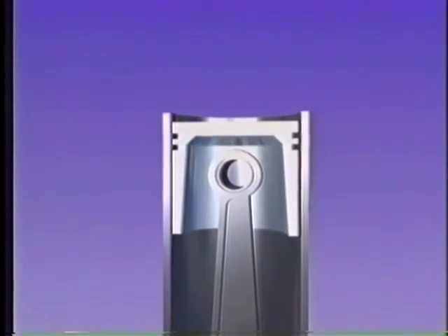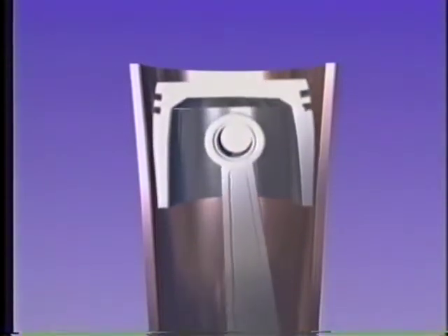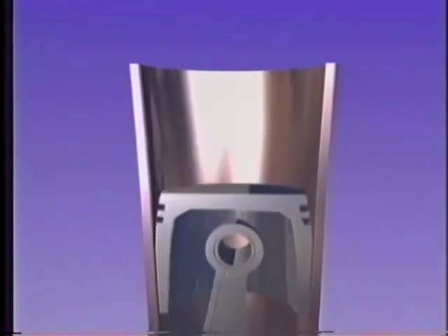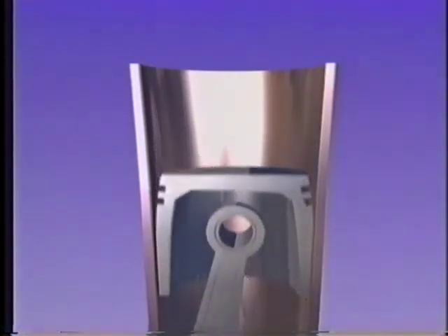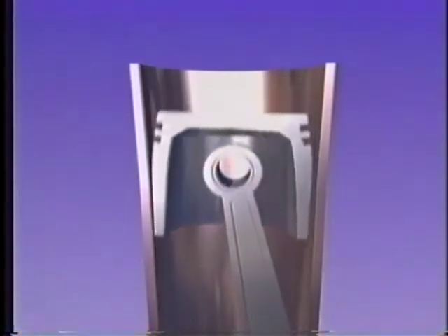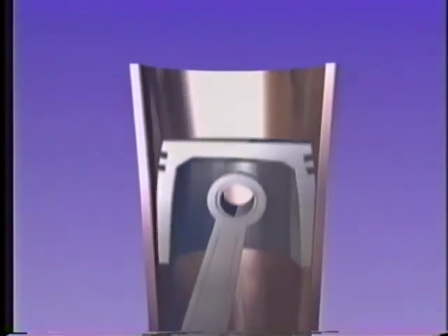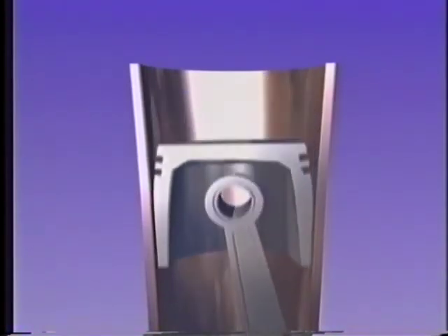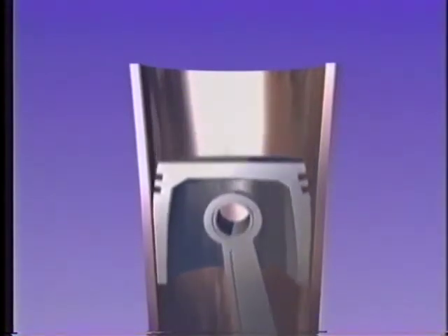Shown here are the deformed cylinder liner and piston shape caused by temperature and the piston side force and tilting motion. Based on these results, further calculation steps in GLIDE simulate the piston ring dynamics and calculate blow-by and lubricating oil consumption. Linked with finite element calculations for cylinder liner deformation, the optimization of lubricating oil consumption can be performed.